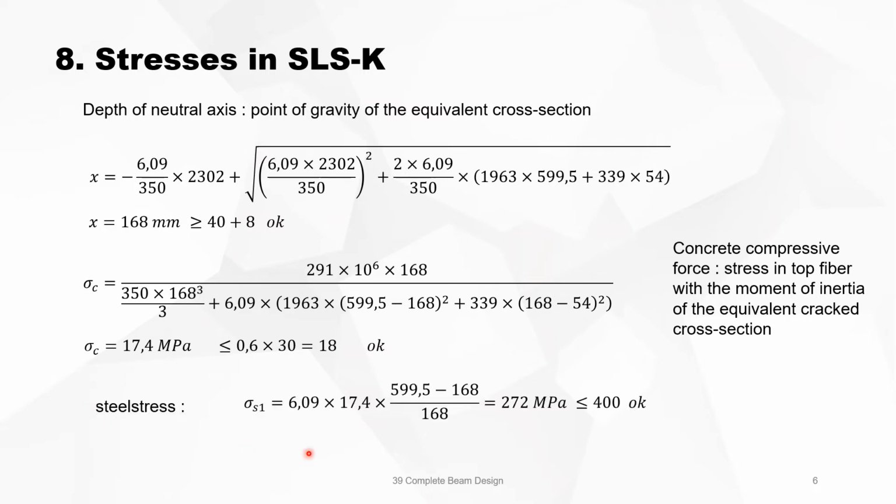When we calculate the steel stress, we'll see that we have 272 megapascal, which is far below the 400, and the steel stress in the compression reinforcement is also far below the maximum of 400.